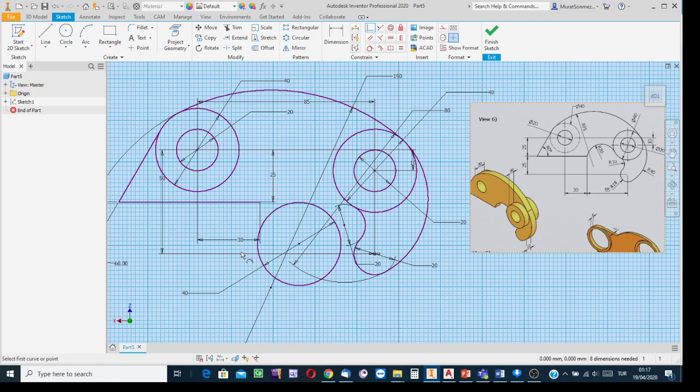In AutoCAD there is such a trick, but in Inventor, if you indicate the center, then Inventor will understand that that point is the point to coincide. If you indicate a circle at any point along the circle, move the cursor to the vicinity, and after seeing this color changing, make a click. Then any point along the circle will be coincided with the other. There is no trick in Inventor.